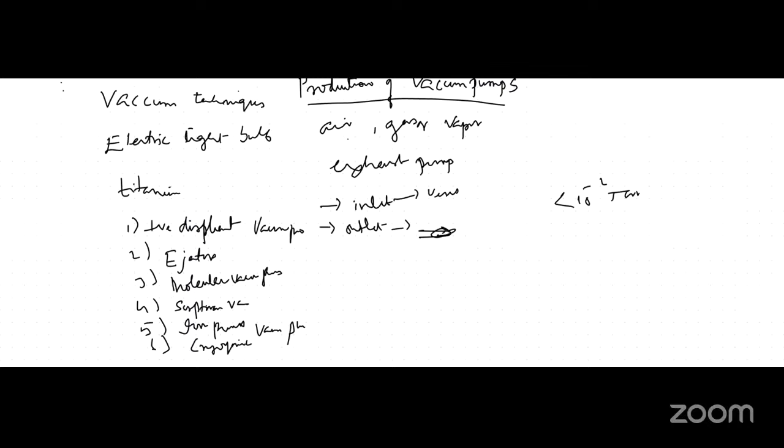That means its temperature will come down. It freezes the specific gas at set cryogenic temperatures. The stages are connected to a sealed cryogenic refrigerator run by an external compressor. The refrigerator cools the stages to a very low temperature, around 65 to 100 Kelvin. The main function of this stage is to capture water vapor.